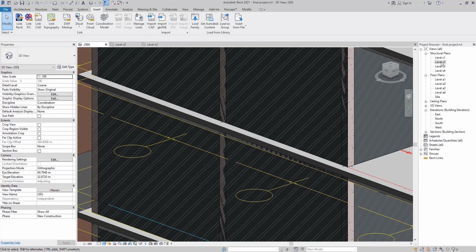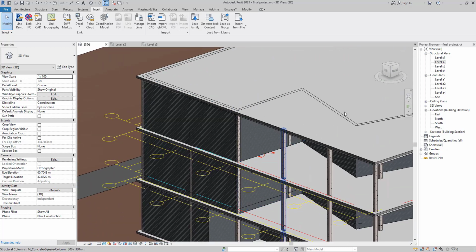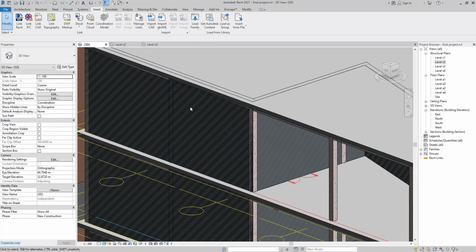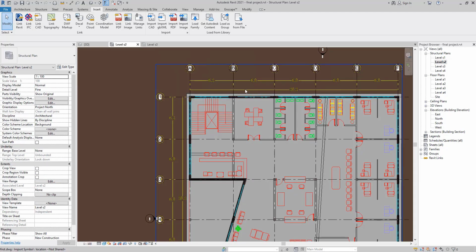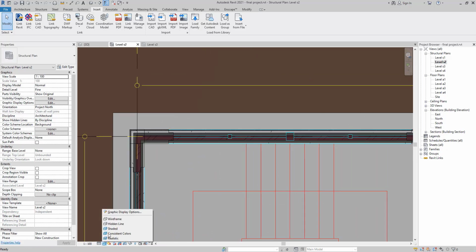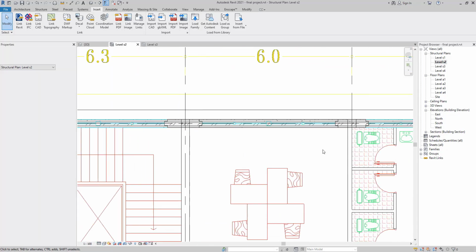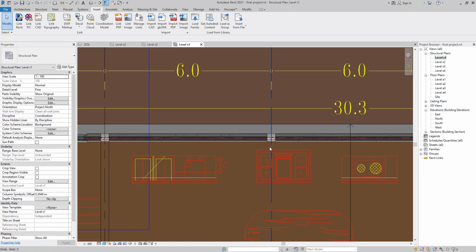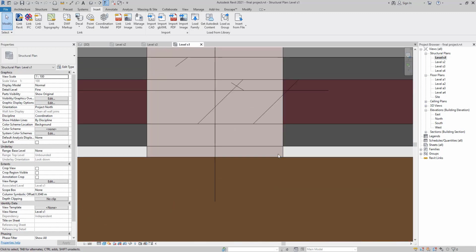So there is also one setting that we need to do, which is changing the location of our wall or even our column, because as you will see it's overridden, because we chose a very big size of the column, and it shouldn't be like this, because as you will see here we need to change the hidden line. For example, on the first floor, as you will see, your column cuts the material of your exterior layer like your facade. It shouldn't be like that. Your column should end at your facade.